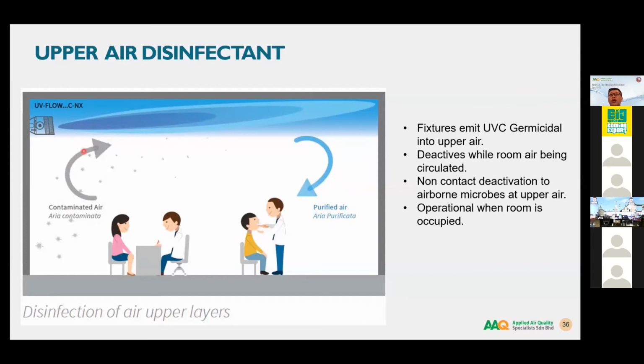Because as you know, UV is harmful to humans and any living creature. We are not supposed to be exposed to UV rays. Ultraviolet ray is harmful. You can get skin burn or skin damage, or maybe skin cancer with prolonged exposure to UV. Of course, not in a short while, but after long hours. Then there is temporary blindness, red eye, watery eye, and also permanent blindness if you don't take it seriously. So wearing PPE is very important.